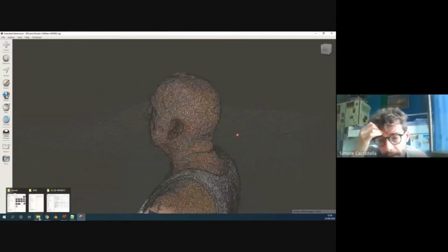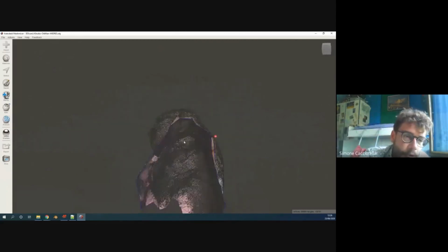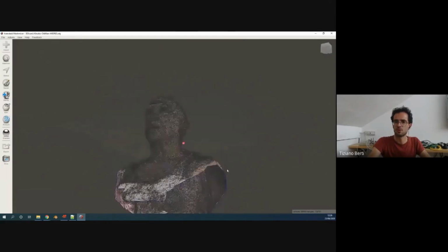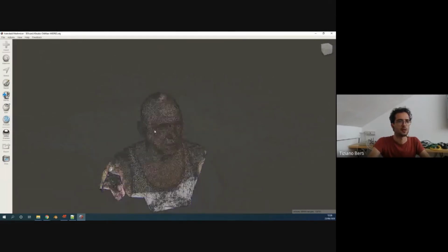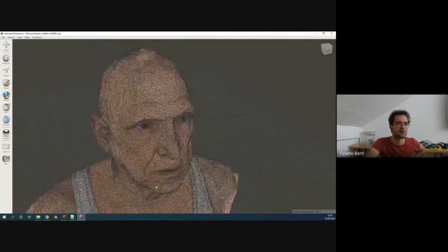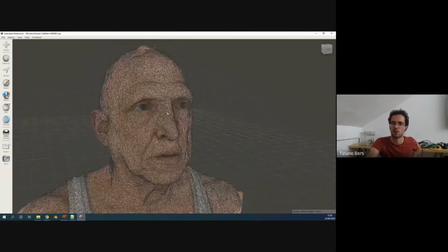We don't have to repair the mesh when we open it from Zephyr? Actually, this part we don't need to be closed, so it's perfectly fine like this. We just have to repair it if we have a hole in the part we are working on. So if we are making a mask, we will just care about defects in this area.